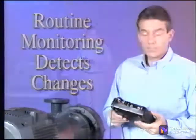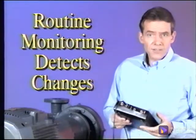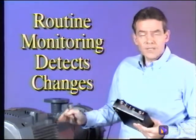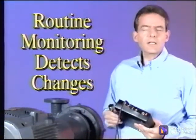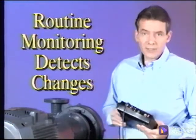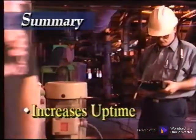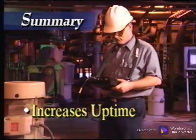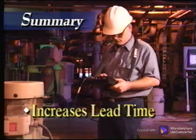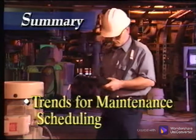The damage caused is often much more severe and costly to repair than problems corrected at an earlier stage. However, when a machine is routinely monitored on a periodic basis, variances in the data indicate changes in the machine. These changes can be analyzed, and the problem can be determined, allowing ample time for ordering parts and scheduling a downtime. In summary, routine periodic data collection and analysis yields increased uptime, decreased maintenance and repair costs, increased lead time, as well as a trend useful for determining machinery life expectancy.